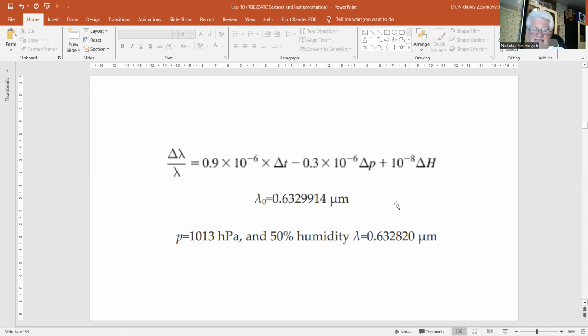The resolution is set by that of the interference pattern measurement, either in time or in the spatial domain. The accuracy depends largely on the accuracy and stability of the wavelength, the distance between two consecutive fringes. The wavelength in air varies, but non-linearly, with the index of refraction, and hence with temperature, pressure, and air humidity.